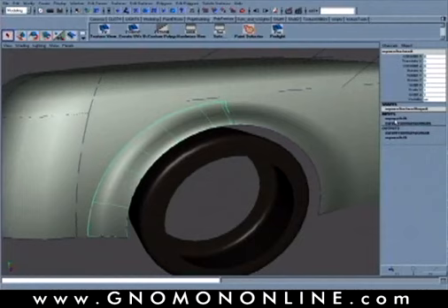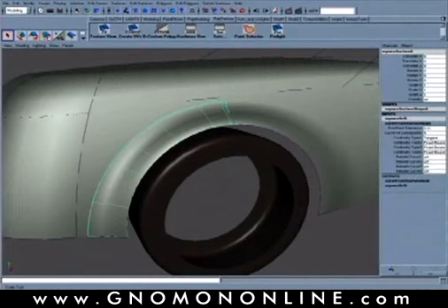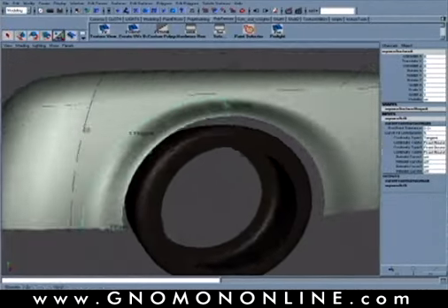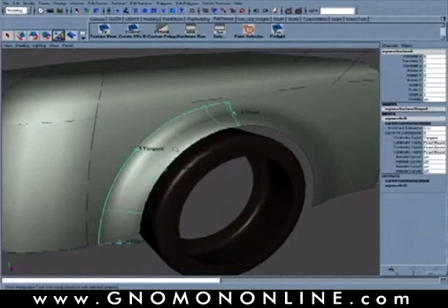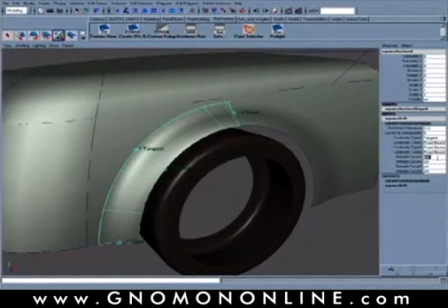Meaning if I grab one of these edges, the square surface that I just created, and I go back and hit T or show manipulator, I can find that that one surface is labeled tangent again, and that is edge number 1. Maybe I want to clean up this edge a little bit, reduce some of the isoparms by rebuilding it. Usually one rule for rebuilding is to do it on a trim edge. Okay, so rebuild curve number 1. So I'll come over to the channel box, rebuild curve is off for all of them, and I'll turn that one on. And you'll see that we'll reduce some of the data that's happening in between here.